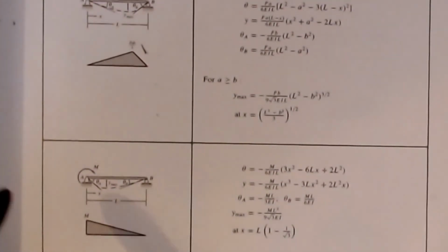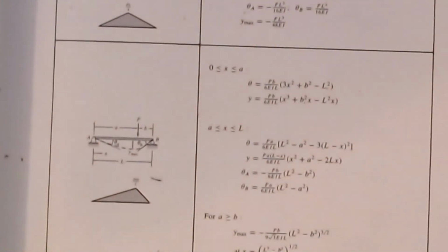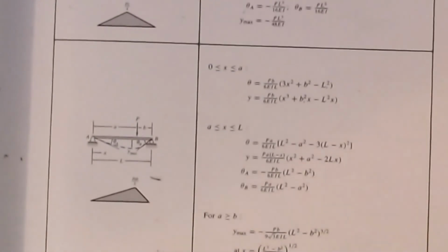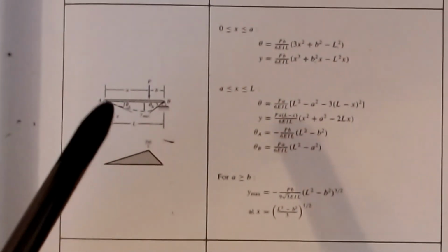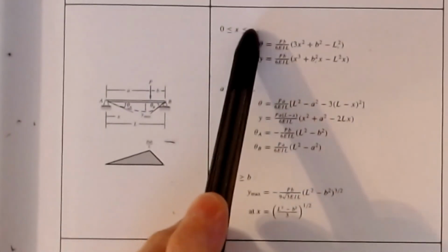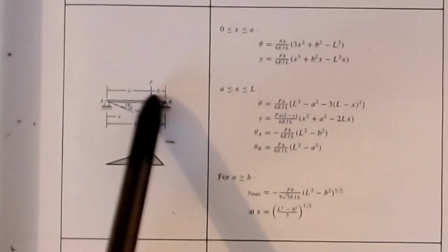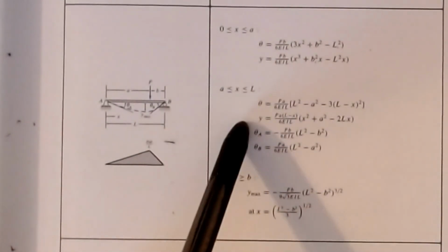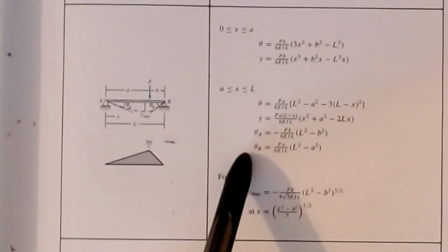Maybe you need something with a moment on the end of a simply supported beam, or a point load that is off center. Now, something that's interesting in some of these cases, in particular with regards to the point load, is that again, we've got our regions, 0 < x < a, and here are my equations, and then a < x < L would be the region over here, because the curve is not the same on either side of this. And likewise the slopes at a and b are different